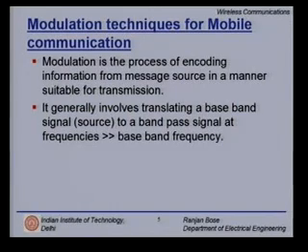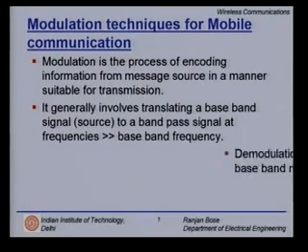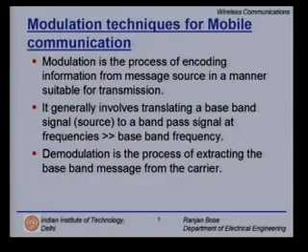It generally involves translating a baseband signal from the source to a passband signal at frequencies which are much greater than the baseband frequency. The demodulation is simply the inverse process. It is the process of extracting the baseband message from the carrier.